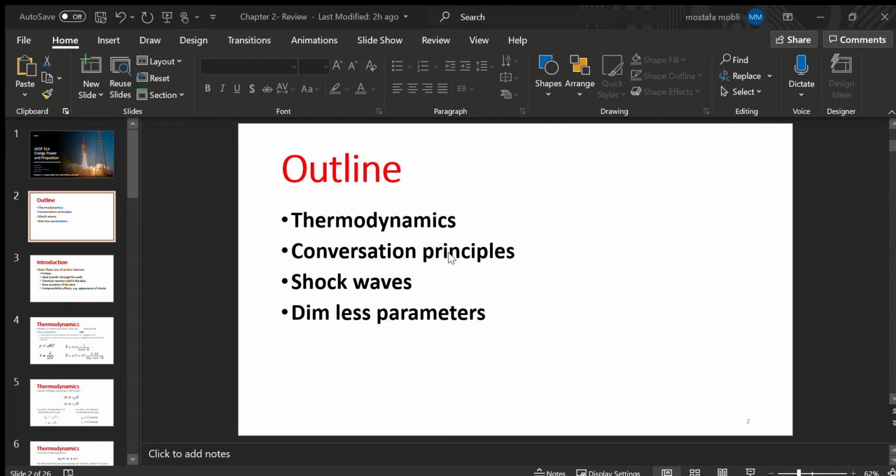We can define the second law of thermodynamics using the Clausius inequality: TdS, the temperature of the system multiplied by the change in entropy, is greater than or equal to the elemental change of heat. But what is the case of equality instead of inequality, right? What is the condition where TdS is going to be equal to delta Q? When you're dealing with a reversible process, right?